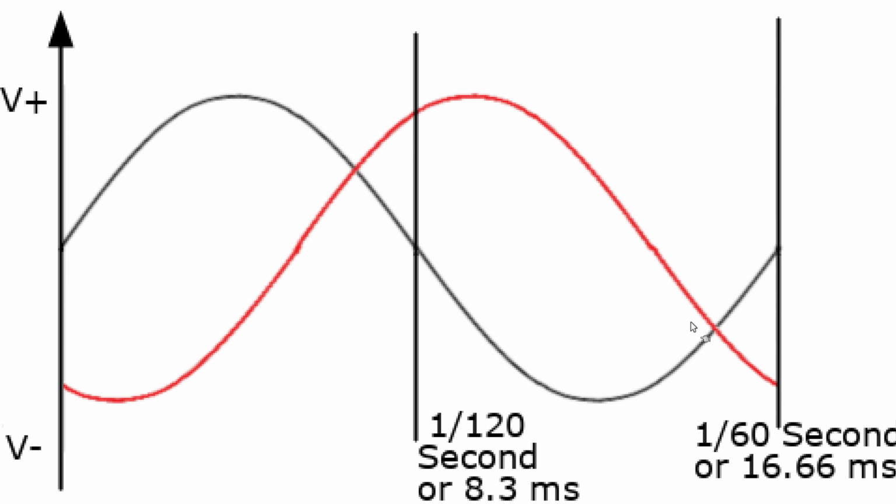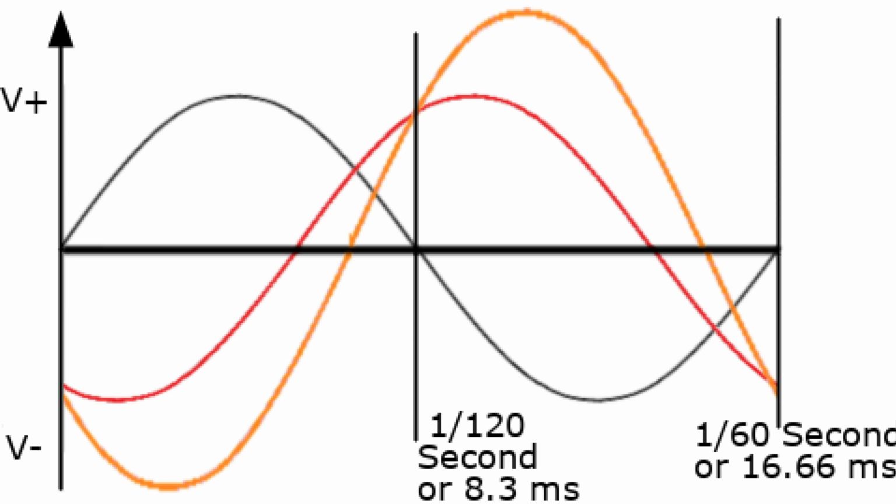So if we were to draw out the difference between these two wires as an additional sine wave, this would indicate the voltage between the two wires. Again, measuring from wire to wire. And it would look like this orange line. Here, the black line would represent the black wire because, again, we're measuring the distance from the black wire.